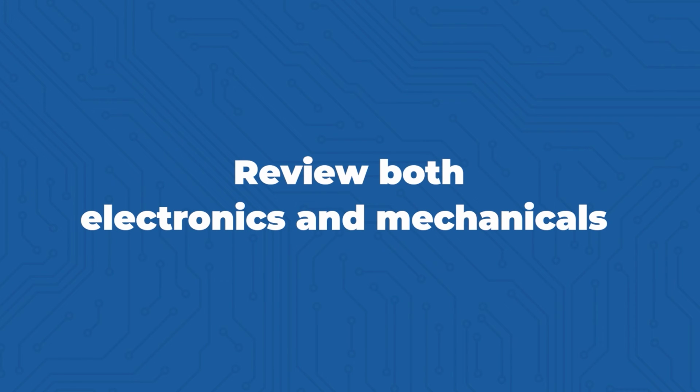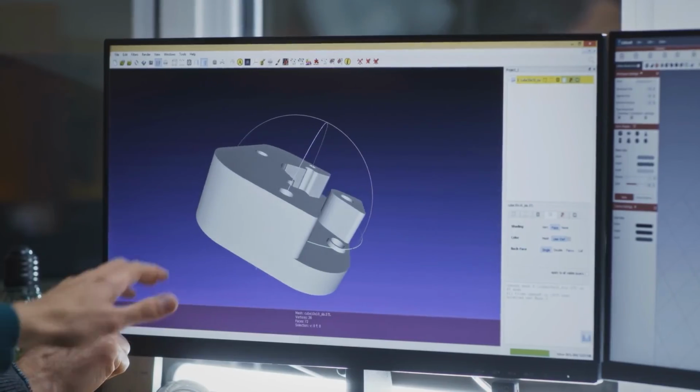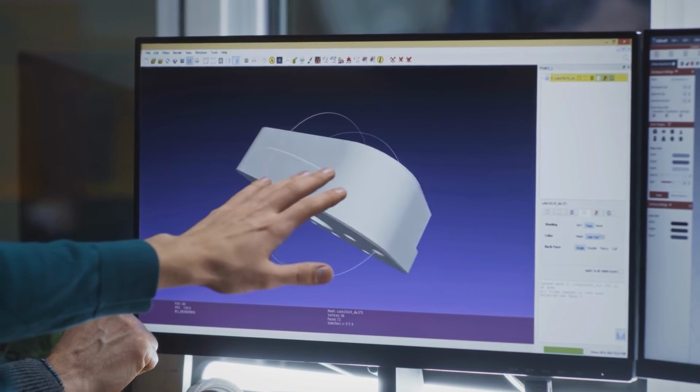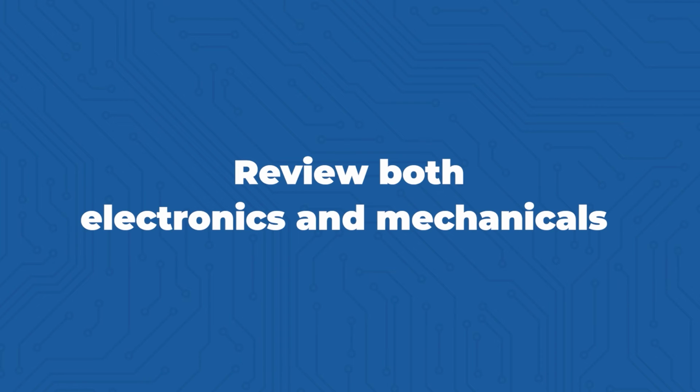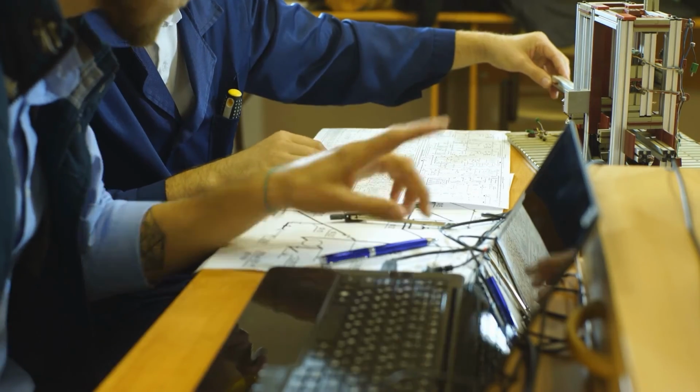These independent design reviews should definitely be done for the electronics, but also for the enclosure. The enclosure would be mostly a review from a design for manufacturing standpoint, looking at the things that we discussed. Can it be a simple pull mold? Does it have uniform wall thickness? Does it have draft? Does it have any side actions? Those are all things that an independent design review can help you identify and eliminate, if they haven't been taken care of in the enclosure design.